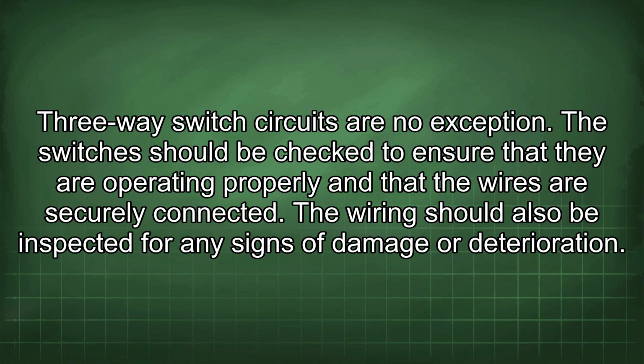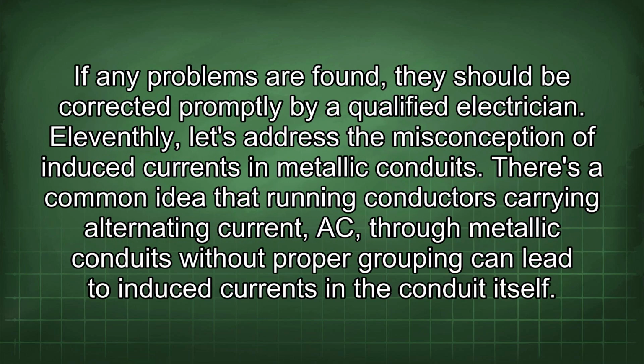The switches should be checked to ensure that they are operating properly and that the wires are securely connected. The wiring should also be inspected for any signs of damage or deterioration. If any problems are found, they should be corrected promptly by a qualified electrician.